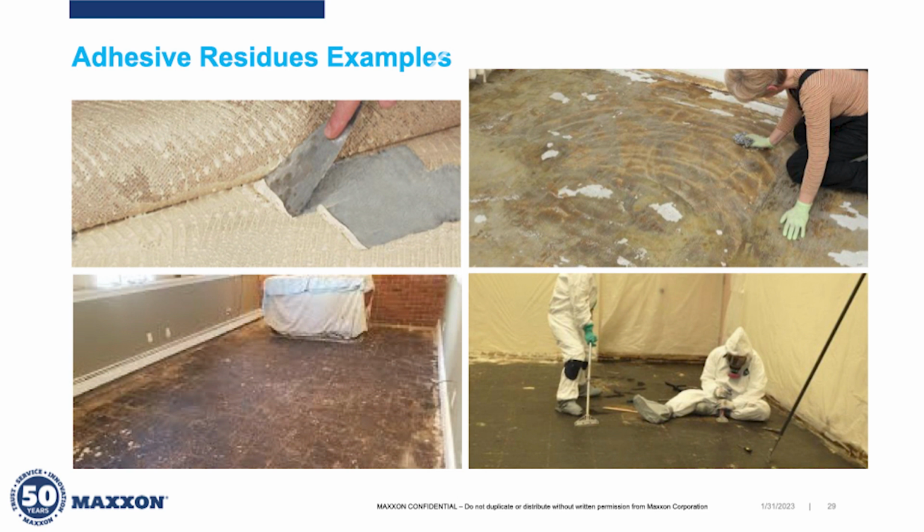These are really aggressive, tacky adhesives that are meant to allow for the removal and reapplication of floor covering, so they stay tacky. And you can imagine when the floor covering is removed, depending on the degree of tackiness that's left, this can prohibit foot traffic through that space. So if it's an office space that's under renovation, it can definitely affect the traffic patterns of that office space, because it will literally pull your shoes off as you cross over it.